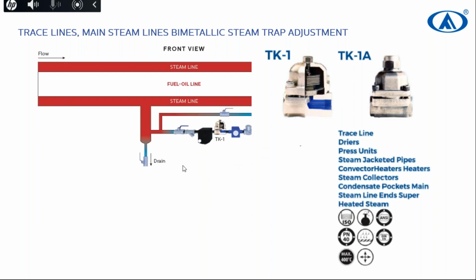For steam trap types, SK, we have different types of thermostatic capsules, which are S, H, and L. How must we choose? S is standard. It means 10 degrees Celsius temperature difference. As a standard, it is S. If it's high, it means 5 degrees Celsius. If it's low, it means 20 degrees Celsius. If you need high discharge, the difference is 20. Low difference is 5. It's up to this. So you can select S, H, and L.